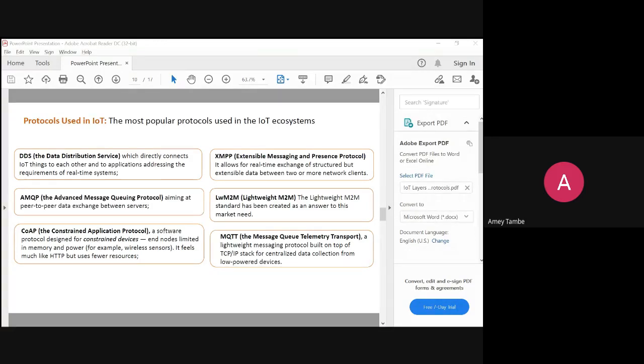So in a smart pole kind of condition, if that particular device or set of devices is equipped with a battery and it is taking up the battery power, then of course we'll require some kind of protocol which takes very little power in terms of consumption and can give you proper throughput. So there is a good choice, that is MQTT.